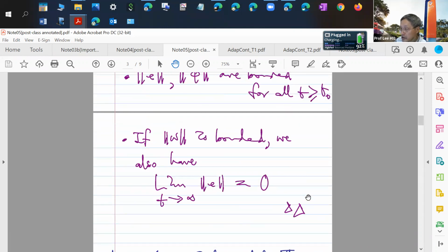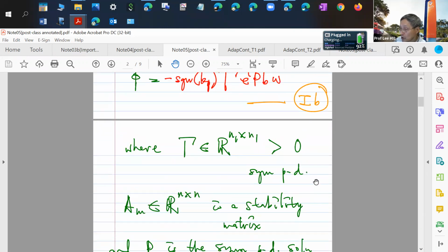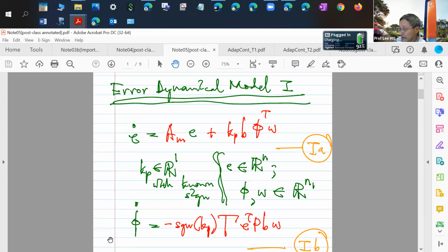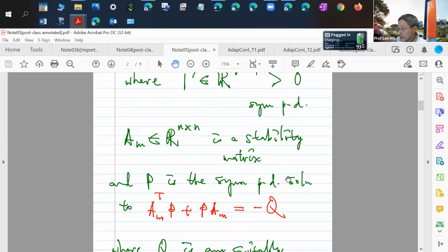adaptive controller. Even though we took it from, developed it from adaptive control with full state variable measurable, actually you will see that the robotic control equation for adaptive control of the Hamiltonian systems of robotics can be rearranged looking exactly like this. And you can do adaptive control essentially even on your revolute joint robot once you cast it in this particular form. Right, so it looks like that.